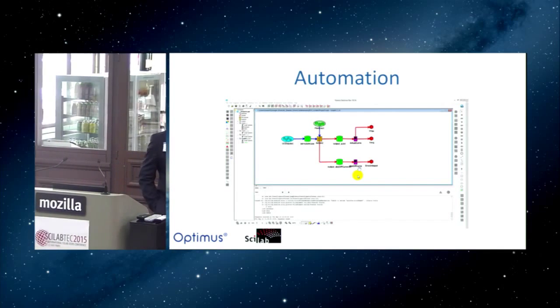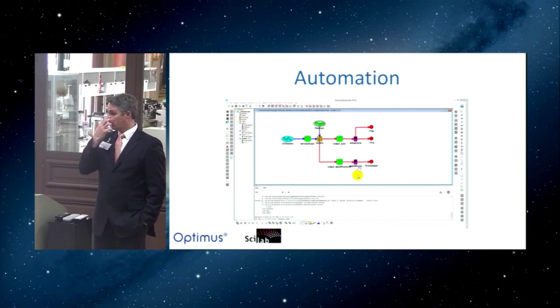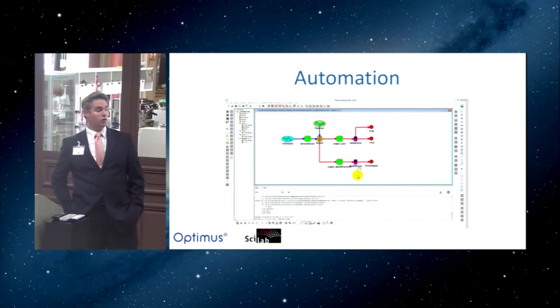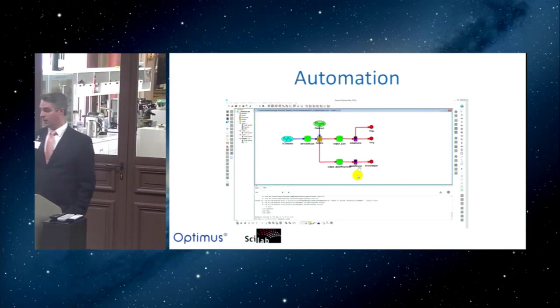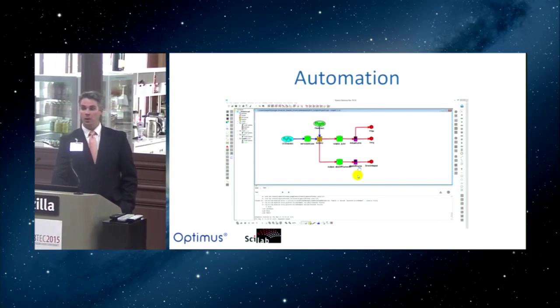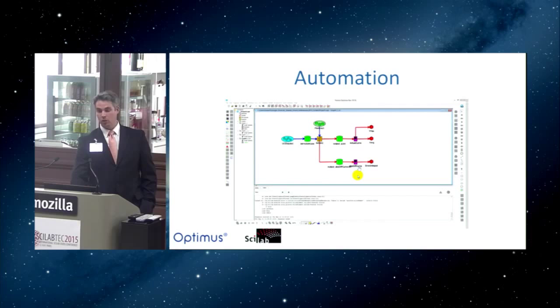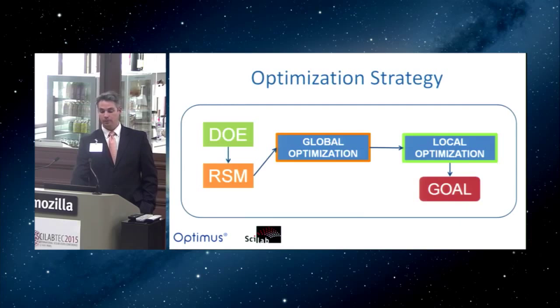It's not transparent. In our case, Scilab was launching a few curves just so we could monitor the process with each experiment, but in this particular case, we did a design of experiments that ran 100 experiments completely unattended. So with about 5 minutes worth of time to set up the workflow and 3 button clicks to launch the design of experiment, we come back an hour later and we have all 100 runs done.